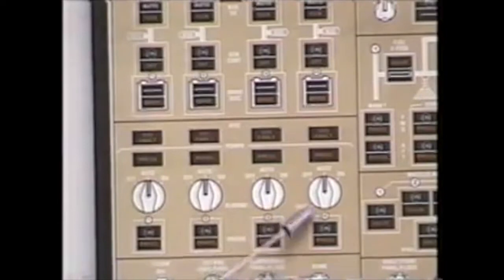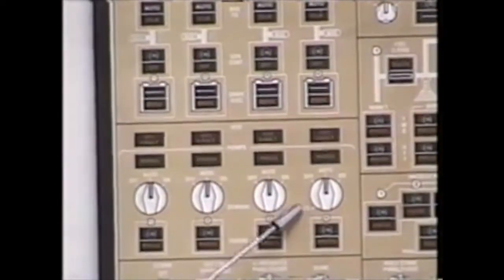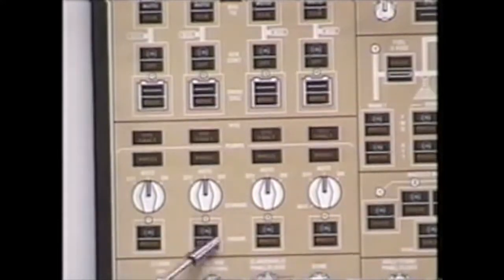The aux pump in System 4, again, is the electrically driven hydraulic pump to allow maintenance to build pressure in your system to tow the airplane. That aux pump is powered by the ground handling bus. EDPs for each engine is engine-driven pump. If the engine is turning, the pump will be turning unless it seizes.